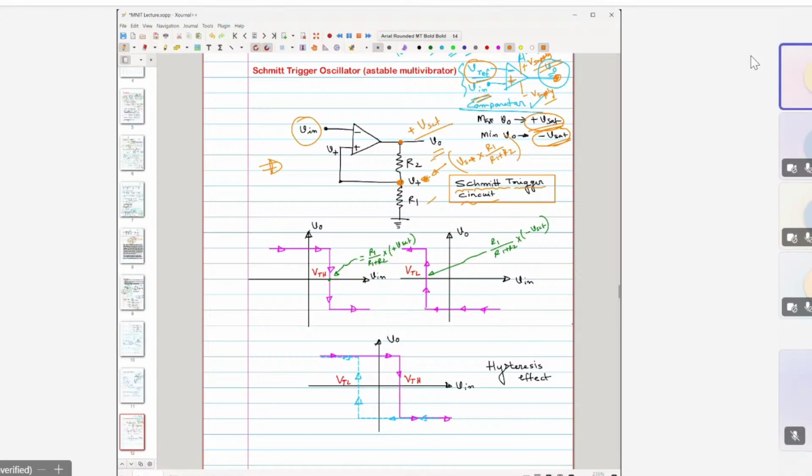And this voltage has been given as an input to the non-inverting terminal. Now if you consider this part, it is nothing but a comparator, right? It compares the voltage V in and this V plus. As I mentioned, if this V in is lower than V plus, then the output voltage would be the same as that of this higher voltage. The higher voltage is being applied to the positive terminal, so this would remain as plus V sat.